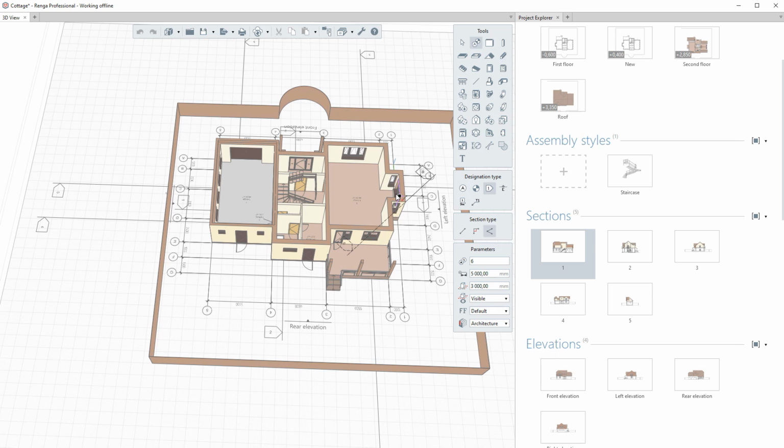For sections, the next parameters are available. Section name. Section line extension. It defines the distance from the extreme handle to the section name. View depth plane offset. It defines the distance from the cutting plane to the view depth plane. The view will not display objects that are completely outside the view depth plane. Object part beyond view depth plane. It determines whether to show or hide parts of objects that are partially outside the view depth plane. Text style and topic.